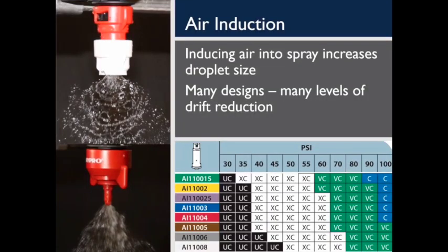Air induction nozzles are the most complex designs on the market, but also offer the widest pressure operating ranges and lowest potential for drift. These nozzles are designed to induce ambient air into the fluid flow via Venturi action. This incorporates air bubbles into the spray droplets, making them larger. There are a wide variety of air induction nozzle variations, and while all of them have relatively large droplet spectrums, they each seek to fill one specific niche or another.